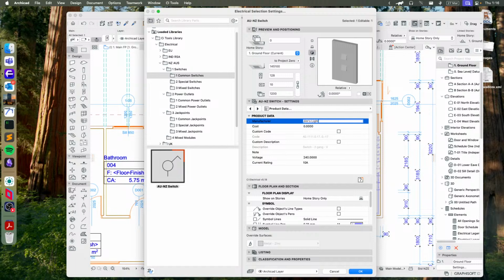And then the last hotspot defines, again, the same as the first one did, the length of the edge. So you can see it's moving that edge out. It's also moving this edge up here, so you can see that going on, but it's changing the length of this edge here. So we can bring that in there. And then now that we have a new edge, all of that repeats again. So we've got the length, we have the, what did I call those again? Reducer, we have the split, then we have the angle and the length again. And then the last hotspot that you can see in here is this one here in the middle, and that will allow us to draw a junction.